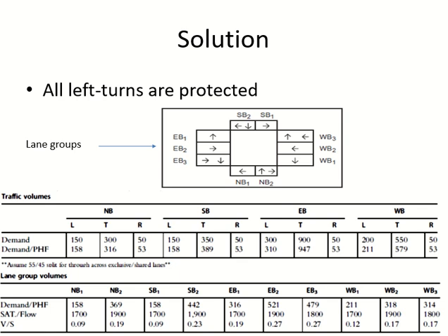About this important demand divided by the heavy vehicle factor, how do we get it? Demand divided by the second table. The numbers are different because these are totals for each movement, while they are for each lane group. So northbound 2 has straight and right both, so this is straight and right both, and about 55 and 45 percent. That only happens here.